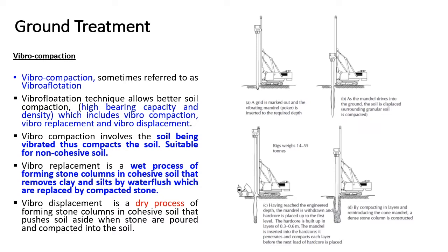Vibro compaction, also called vibroflotation, uses large vibrating mandrels to penetrate, displace, and compact the soil. When the mandrel is removed from the ground, the subsequent void is filled with stone. The mandrel is then forced back through the stone, further displacing and compacting the ground stone. The method produces stone columns in the ground and compacts the surrounding strata, enhancing the ground bearing capacity and limiting settlement. Typical applications include support of foundations, slabs, hard standing, pavement, tanks, or embankments.